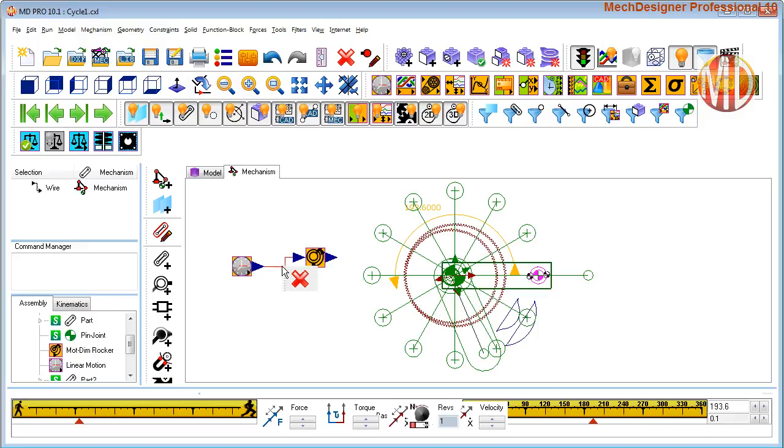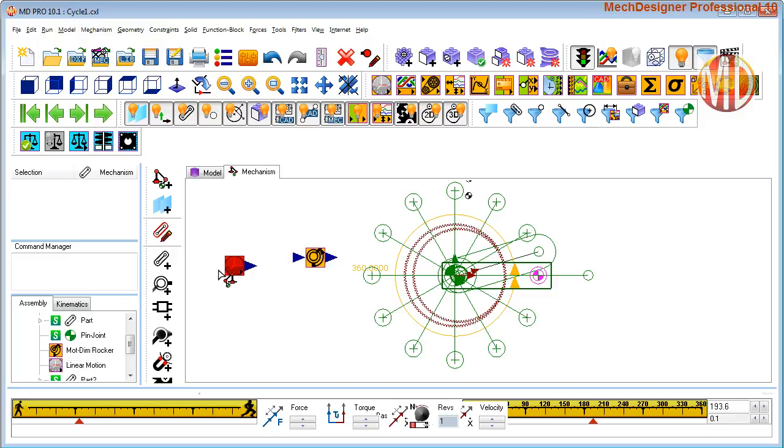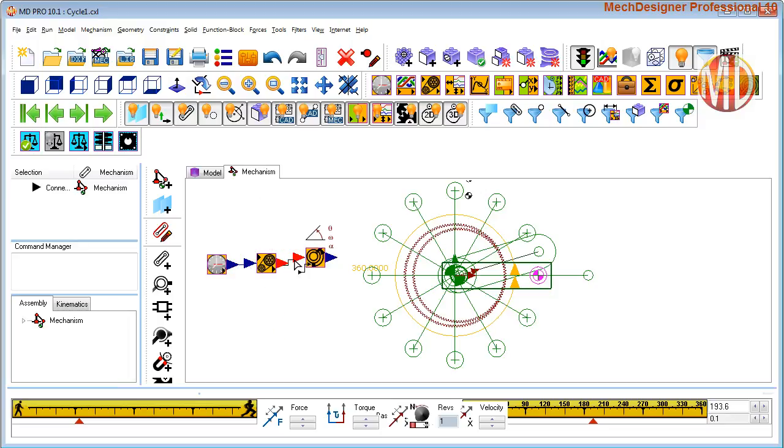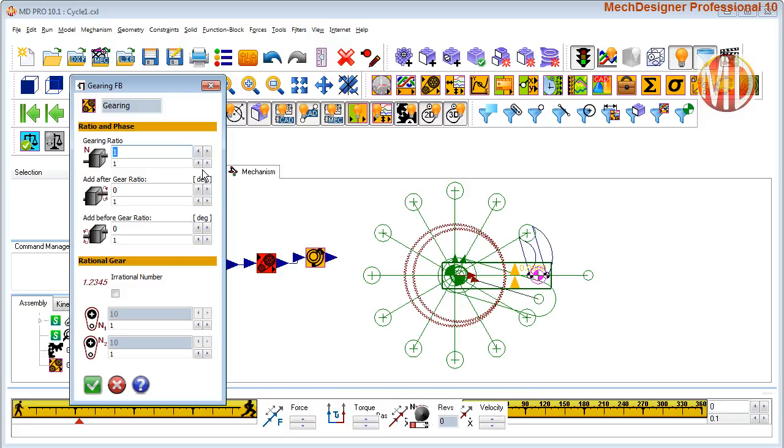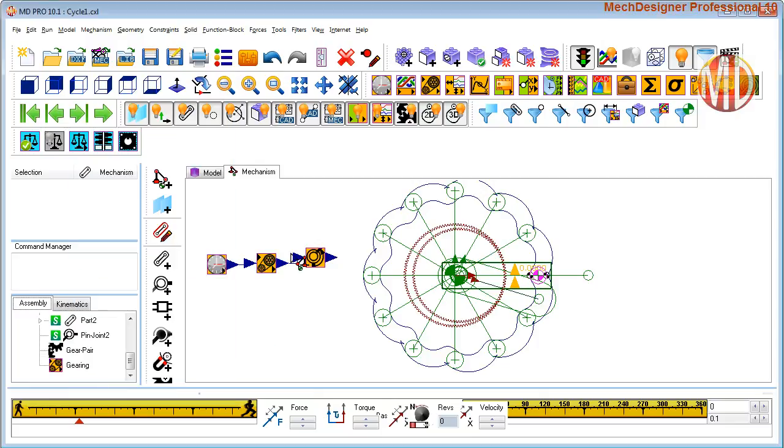So I'm just going to add a gearbox in here, and right click, add a gearbox, and then connect that in. So the machine timing is now going to go through the gearbox, and you'll see the cam come straight back in. And as I increase that, we should see more lobes round. Okay, so we're going around here. Whoops, gone too far. So it's 11 to 1. Okay, so now you'll get a feel.